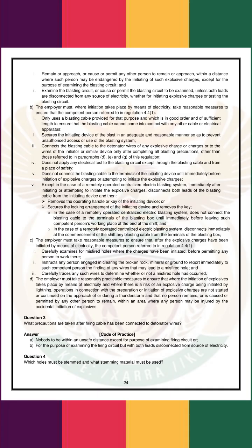Except in the case of a remotely operated centralized electric blasting system, immediately after initiating or attempting to initiate the explosive charges, disconnects both leads of the blasting cable from the initiating device and then removes the operating handle or key of the initiating device, or secures the locking arrangement of the initiating device and removes the key.